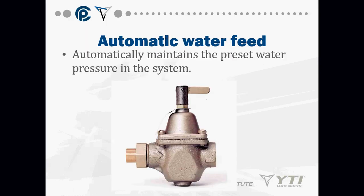Okay, your automatic water feed, that's what it will look like. Again, they are directional. Look at your arrow. So water is coming in through this way and then out to your boiler. To adjust the pressure, this top little doodad right here will come off. You unscrew it, and underneath it is a small little Phillips screwdriver head. Turn it to the right, you increase pressure. Turn it to the left, you decrease pressure.